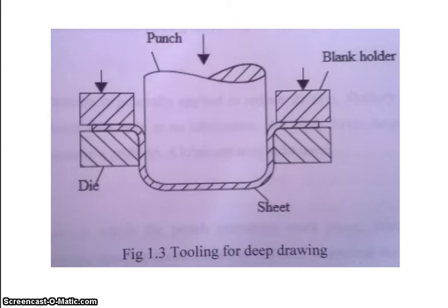Deep drawing. Deep drawing is a sheet metal forming process in which the sheet metal blank is radially drawn into the forming die by the mechanical action of a punch. It is thus a shape transformation process with material retention. The process is considered deep drawing when the depth of the drawn part exceeds its diameter. This can be achieved by redrawing the part through a series of dies.